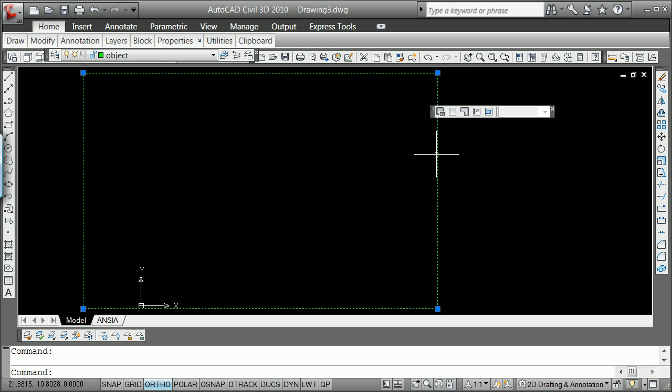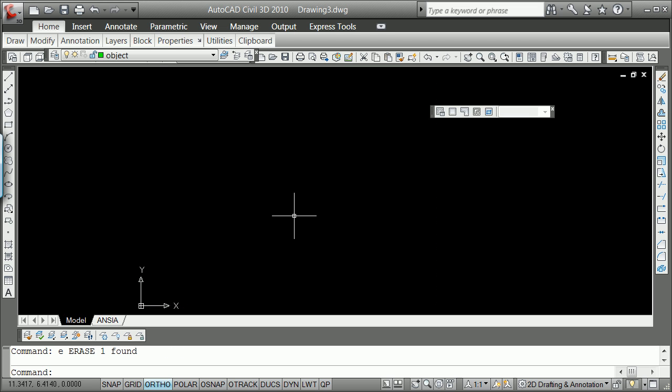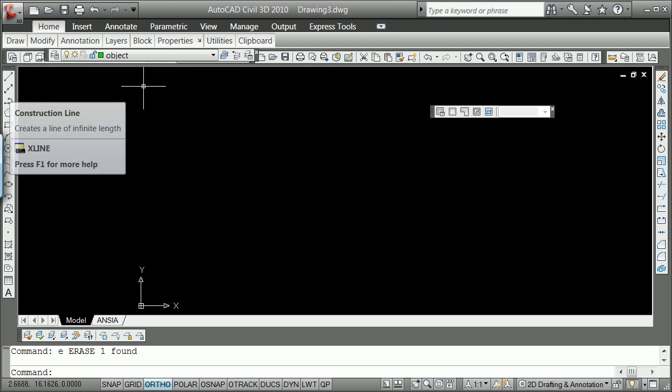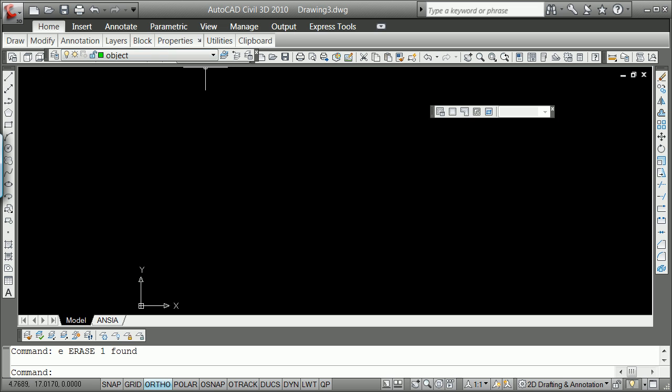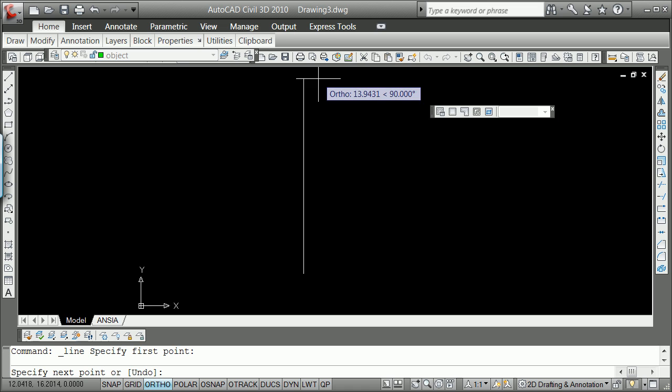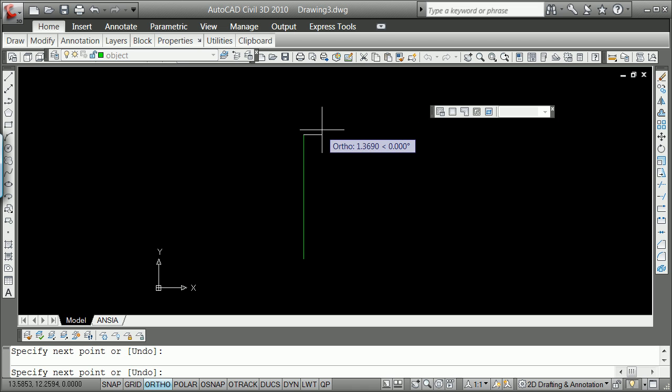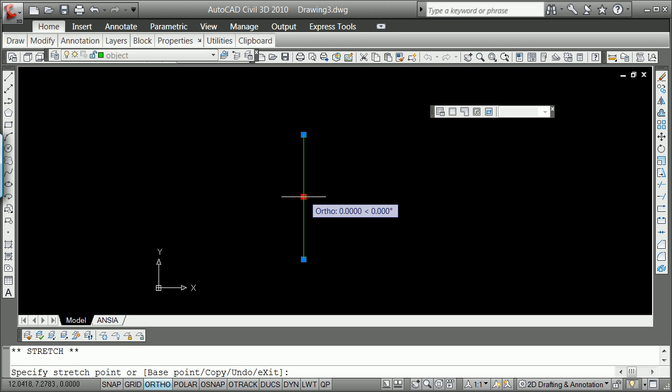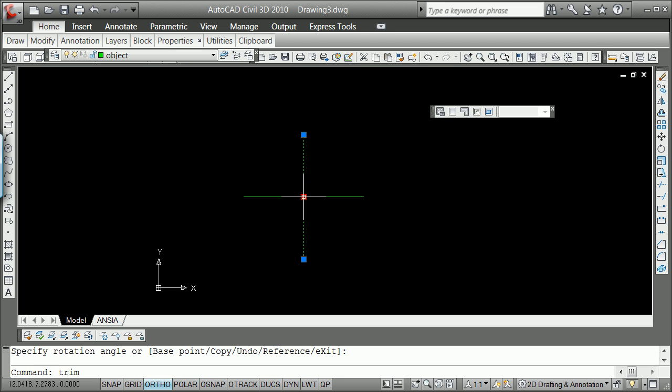You remember, I hope, or consider that very often the geometry of the structure will give you the geometry of the force. That said, I'm not a big lover of X lines, but I'm going to go ahead and use one in a little while. Right now I'm just going to draft an object line, hitting my format. I've gone up just some arbitrary distance here. I am going to then go ahead and turn this. I'm going to left click, spacebar, C for rotate 90 degrees, and I'm going to trim.